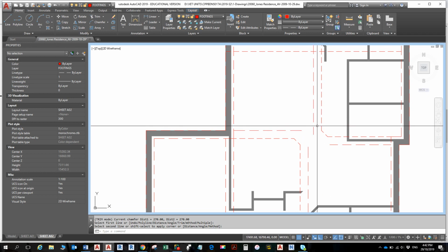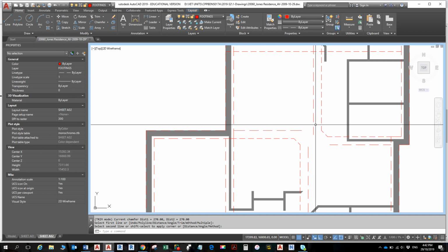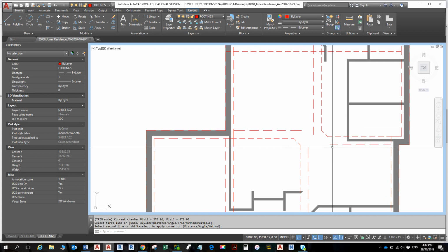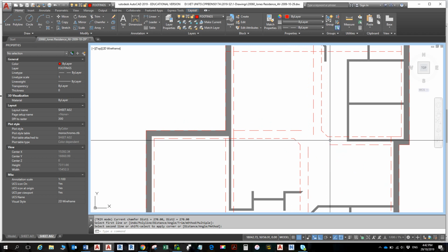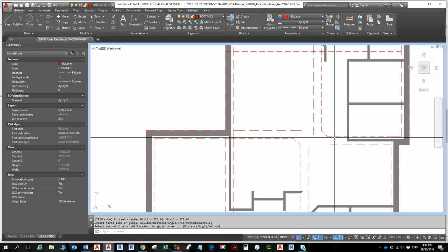And how would we then close these lines up and bring them to meet to become a corner there? What are our options? Isn't it just fillet, or you click on the line and drag, or move? What other ways are there? They're all good, they're all fine. One might be more efficient than the other. Fillet is probably my first choice.